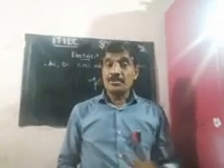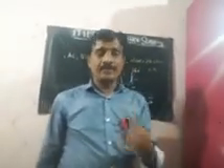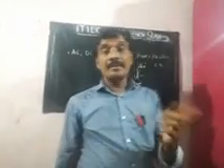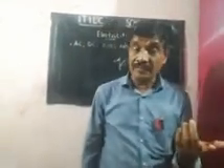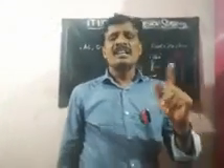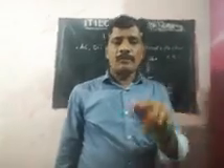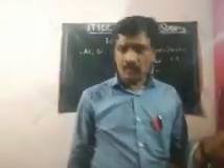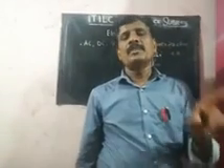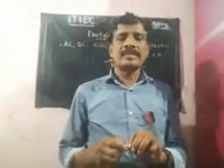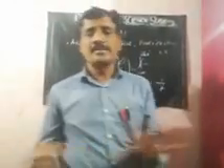For example, if we take 100 volts of AC, what is the energy supplied by 100 volts of AC? The equivalent value of the DC is not at all 100 volts; that becomes 70.7 volts. Let me give one example to clear this doubt.